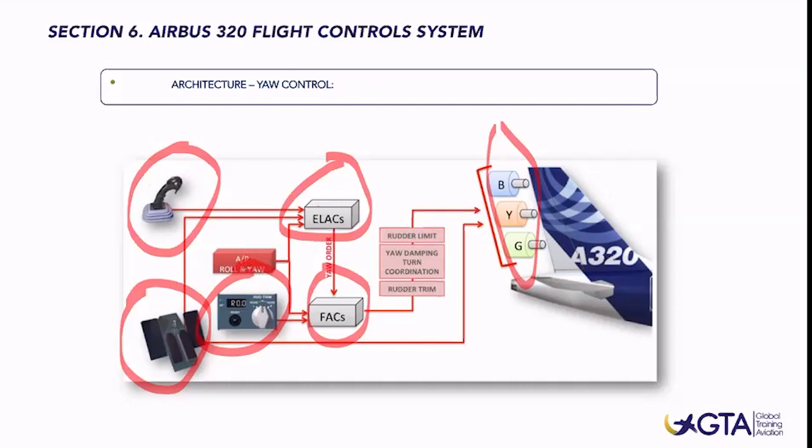Remember that the rudder trim is electrical, and you just have to keep pressing this rudder trim to the nose left or nose right, usually 8 to 10 seconds, depending on which yaw moment we are getting. So we don't need to do some clicks several times. Just keep pressing the seconds that you need, and the digital indication on this display will indicate how much rudder trim you're using.